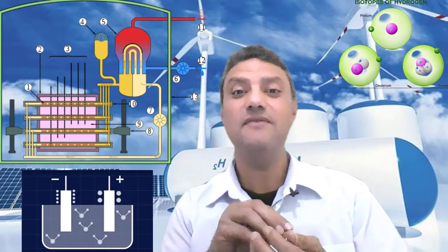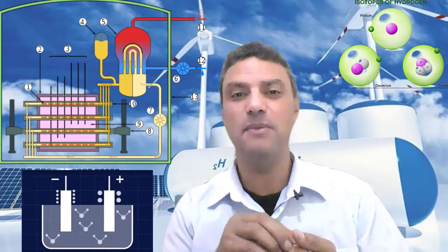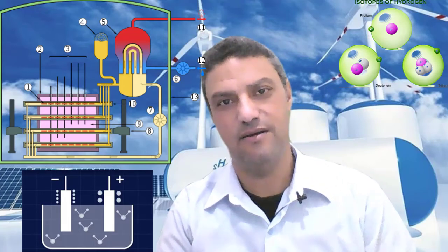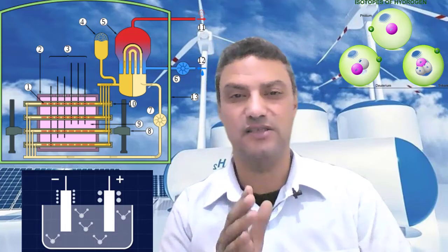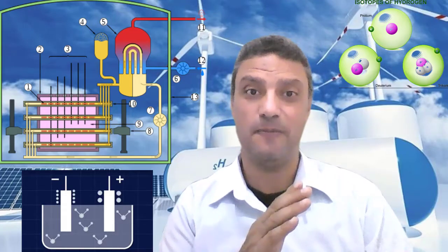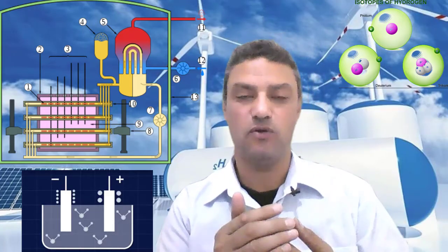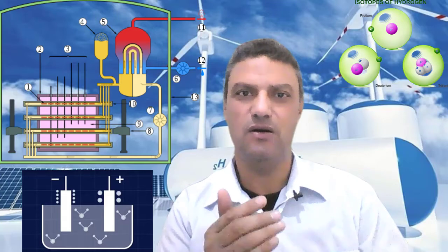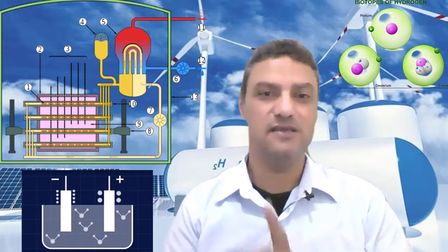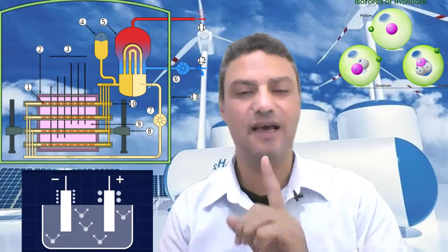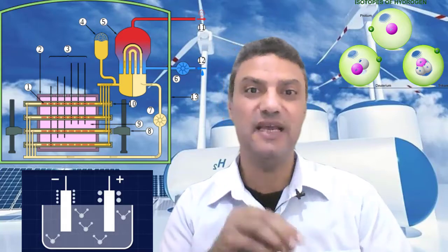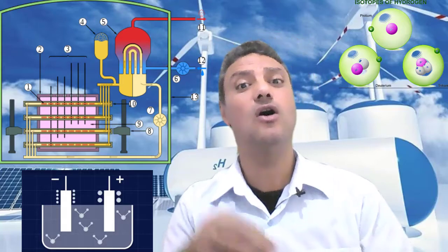Number 7 is the production of hydrogen. The content of heavy water relative to light water is 1/6,000. So the cascaded thermolysis or electrolysis techniques of water produce at the end heavy water. So during the production of heavy water, we get hydrogen as well. Okay, this is one of its unique advantages. So this is behind the reason of adopting CANDU reactors in hydrogen economy.